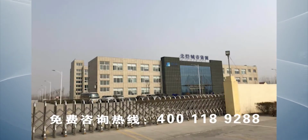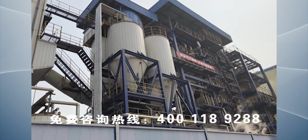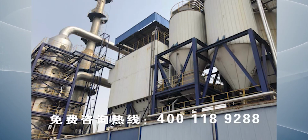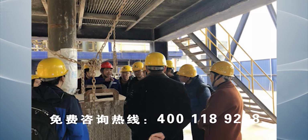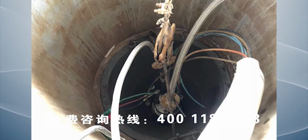The dangerous waste combustion project of Beikong, Bingzhou, Pingfu. Its off-gas treating process is the integration of quenching de-acidification plus bag dust filter, plus denitration, plus water washing, plus off-gas chimney discharge. All the water, including the rain water, washing water, and recycled washing water, is treated by the integration of semi-dry quenching de-acidification.